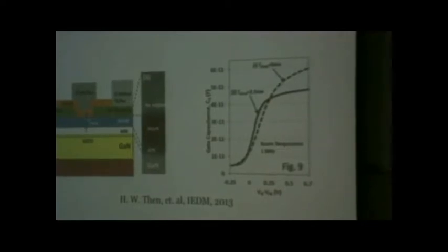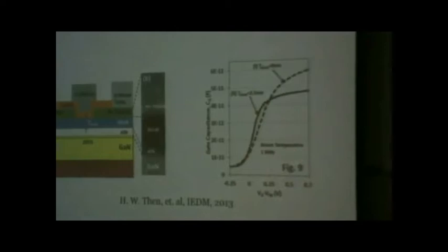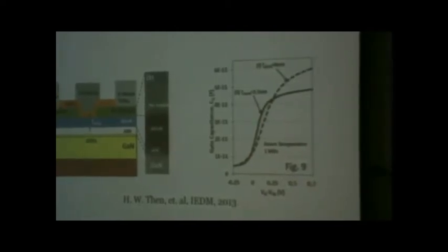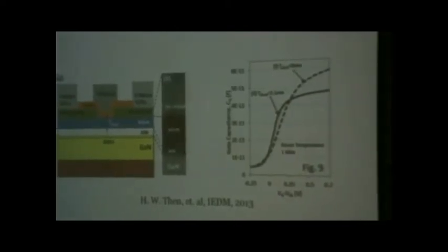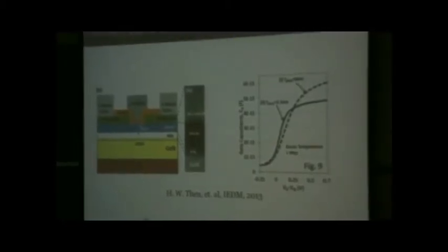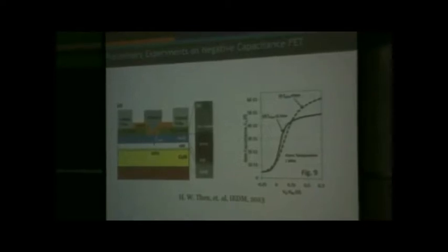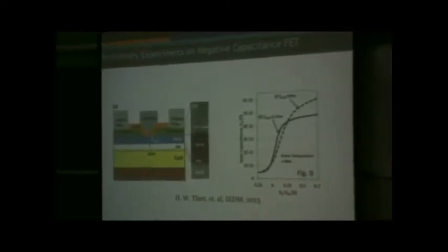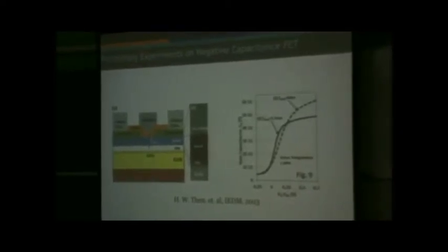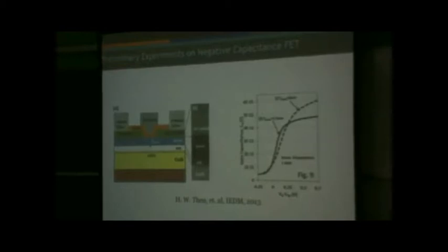Mathematically, that gives you a negative differential capacitance in this region. And it's an Intel experiment, so the data is very clear. There is no noise-related issue that we can see here. But the jury is out as to the exact mechanism. At least in its behavior, it looks like a negative capacitance effect, quote unquote negative capacitance.